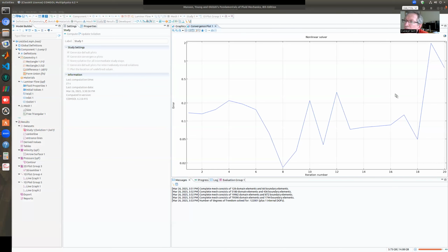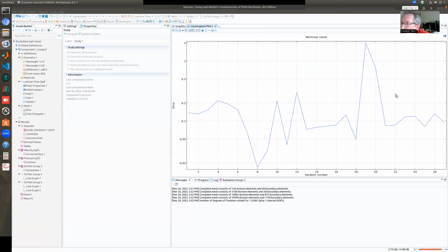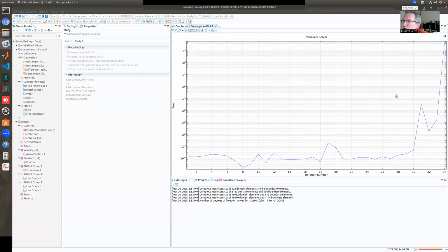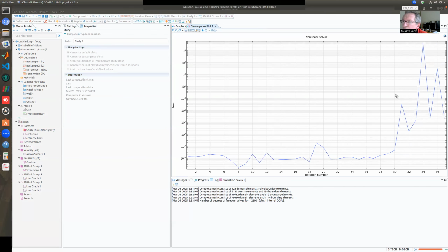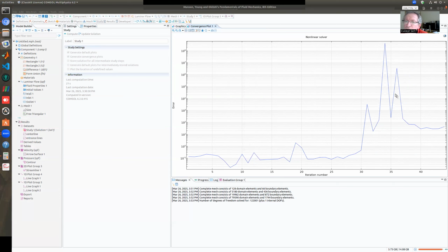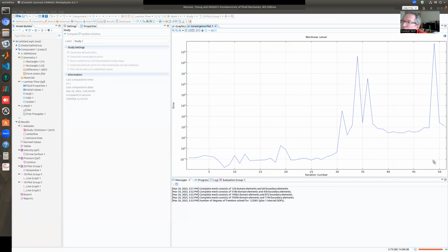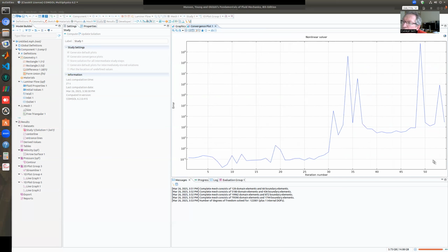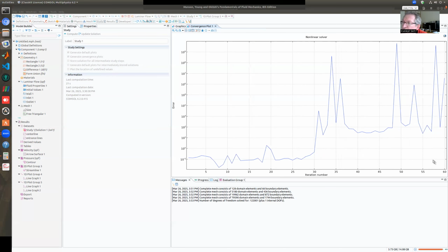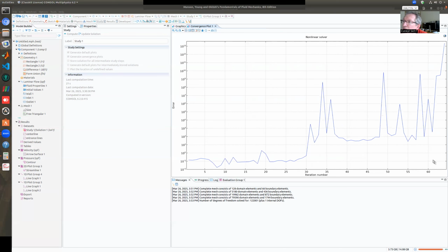This is a harder problem. So we have an obstacle and the obstacle has some sharp corners. So there will be maybe flow separations, who knows? And maybe at the back of the solver, looks like this solution is kind of diverging. It's struggling a lot to converge. I'm expecting these errors to stabilize and go down and become smaller than the default tolerance value, but it's not happening. Maybe just some unsteadiness going on and I'm trying to solve a steady problem or I don't know, something like that, right?